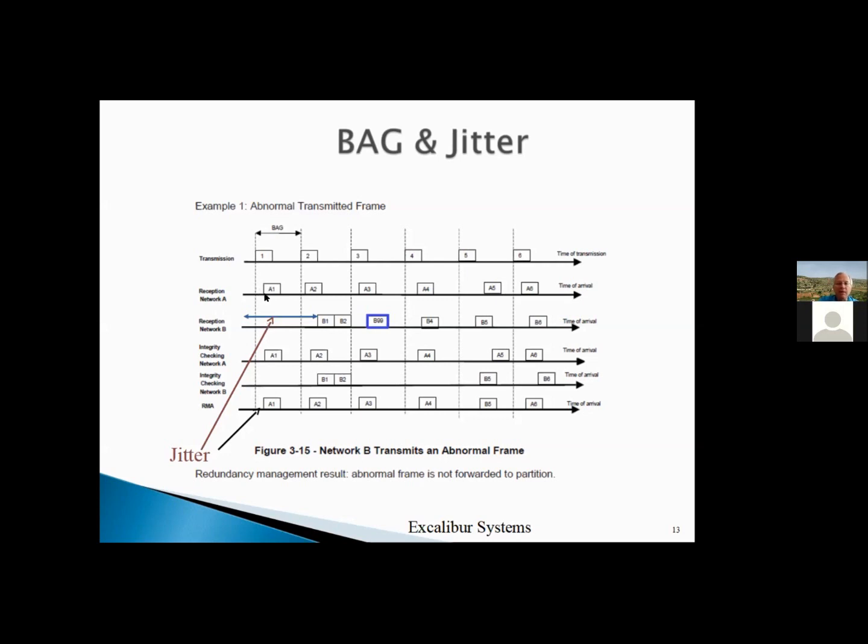So it got to the receiver on the A, got to the receiver here. The B got hung up somewhere and was pushed off a lot. Okay, so the receiver only has A to work with at this point, so it checks that A is okay, that there are no errors in it. And having checked that there are no errors in it, it says, okay, I got it. I've got the first packet sent by end system A. The first packet of the VL, whatever it was, of the altitude, came in, and I'm now going to accept it and send it up to my user.